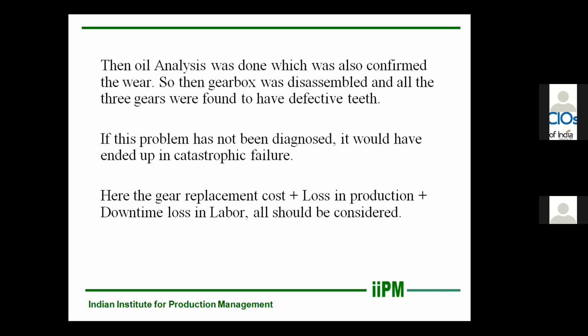And after that, because for evaluation of a problem in a gear, you need to do vibration analysis as well as oil analysis. These are the two analyses compulsory for gearbox analysis. So in oil analysis, it was found that yes, the teeth were wearing out. So the gearbox was disassembled and all the 3 gears were found to have defective teeth. If the problem had not been diagnosed, it would have ended in catastrophic failure, that is total failure of the equipment. So here the gear replacement cost plus the loss in production plus downtime loss in labor, all should be considered.